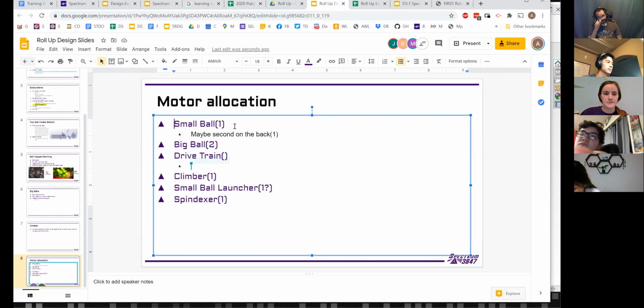Are there any disadvantages to being swerve in this game? You have to make sure you can cross the speed bump in every direction. It doesn't seem too bad. You may need to have little idler things so you can't get perfectly beached in the center somehow, where none of the four wheels are on the ground. But as long as you have something that lets you tip to one side or the other, you're probably fine.